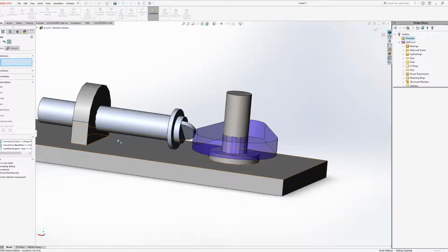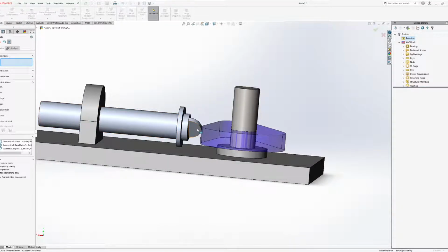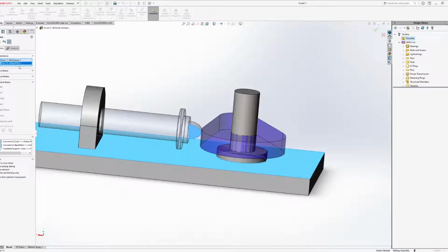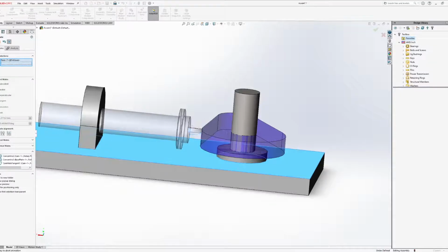It's kind of off-center because now it can rotate in this direction, and do that, unfortunately. So I want to make sure that this kind of flat surface is faced towards the rest of our plate. So I'm going to create a parallel mate between those two.